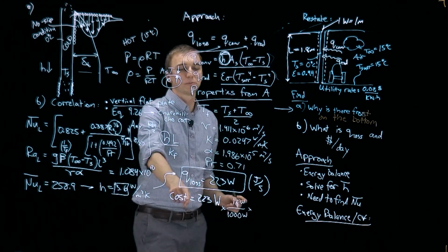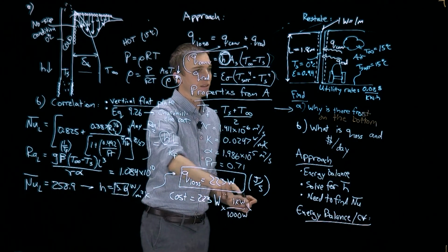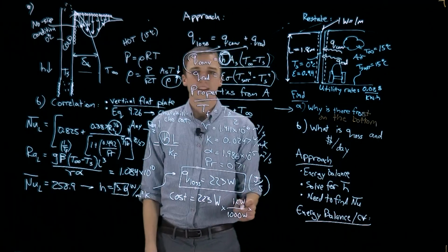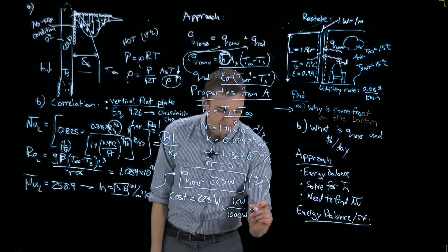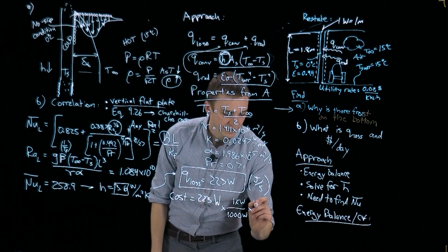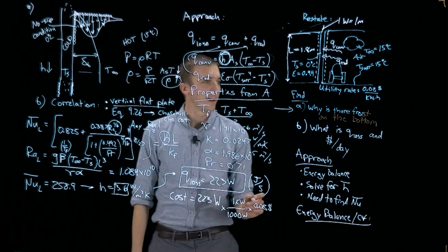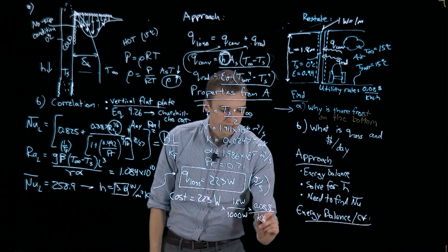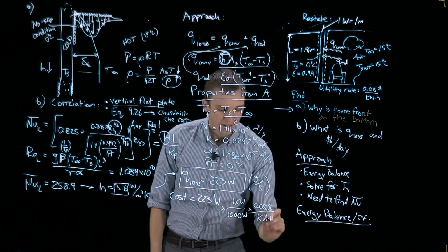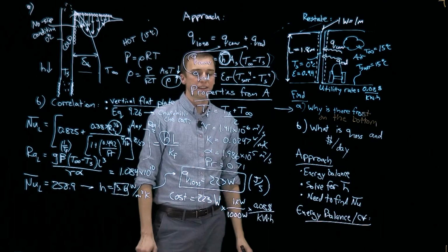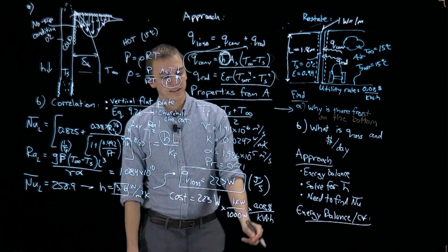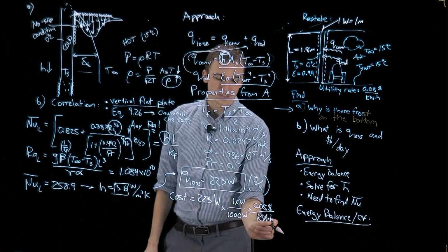Then we're going to multiply our heat rate in kilowatts by our rate, which is how much money it costs us, $0.08 per kilowatt hour. And then finally, this would be on an hour basis, right? Because that's kilowatts per hour.